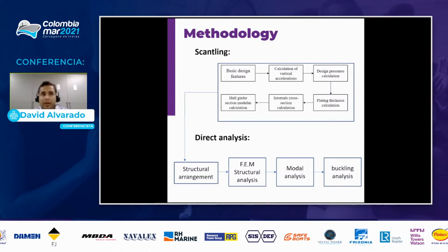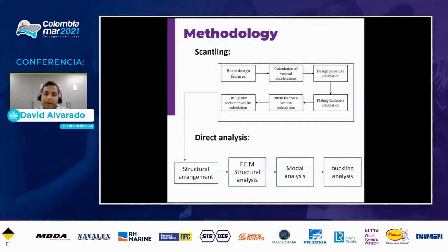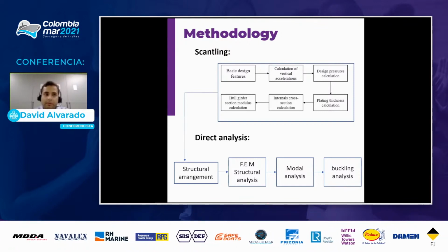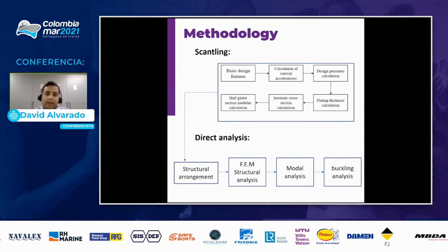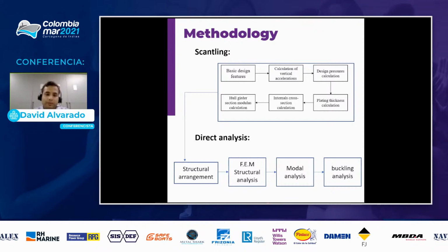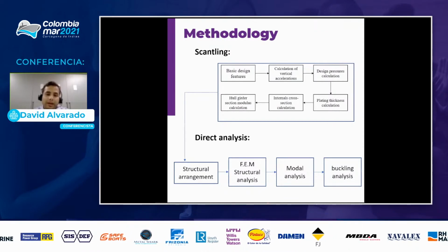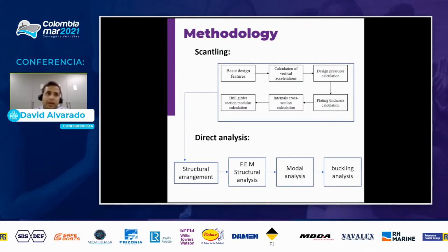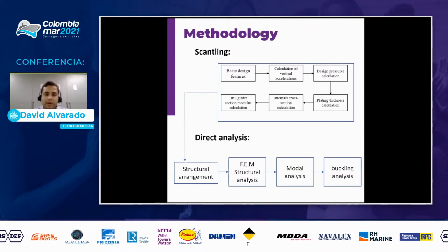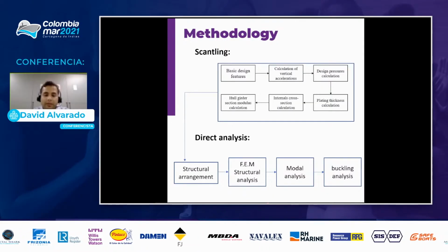Of these design pressures, and given the separation between longitudinal and transversal elements along the liner, we can determine the thickness of the liner, and then we make the calculation of the transversal component in terms of reinforcements. And finally, we do an analysis and a calculation of the midship, which should exceed the considerations given the standards.